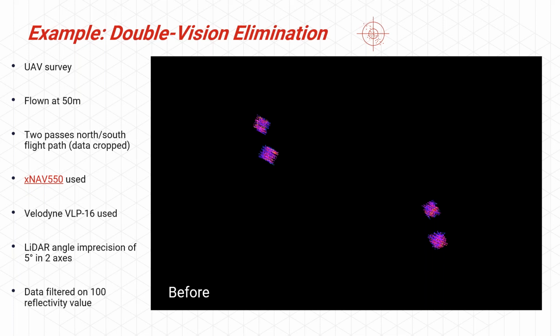It has then turned around and flown south over the same targets. And as you saw before with the red and the blue rectangle, what's happened here is the 2 profiles of this object that it's seen have not overlapped at all, and we've got 2 instances of the same object. But if we boresight this, you can see that we have 2 objects as we should, and they are crisper, they are more square, and they're denser as they should be. And that's really the aim of what we're getting at.